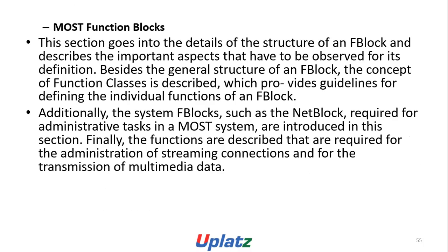MOST function blocks. This section goes into details of the structure of an Fblock and describes the most important aspects that have to be observed for its definition. Besides the general structure of an Fblock, the concept of function classes is described, which provides guidelines for defining the individual functions of an Fblock. Additionally, the system Fblocks, such as NetBlock, required for administrative tasks in the MOST system, are introduced in this section. Finally, the functions are described that are required for the administration of streaming connections and for the transmission of multimedia data.